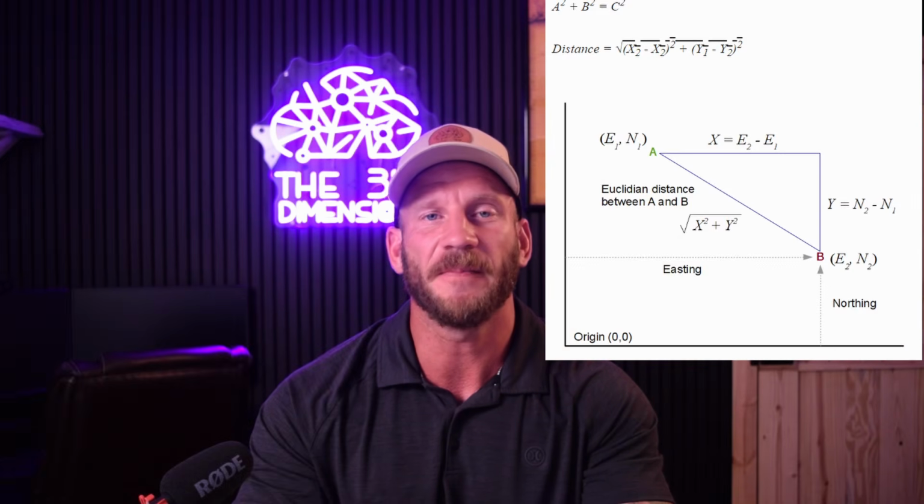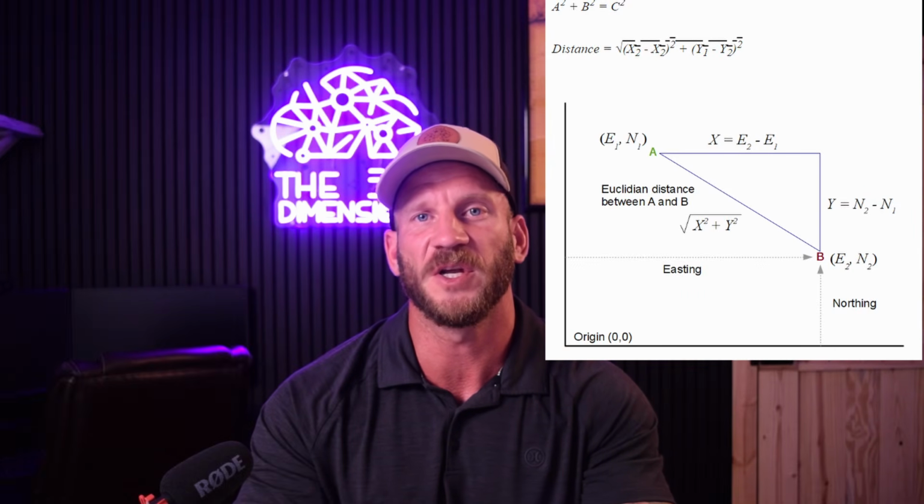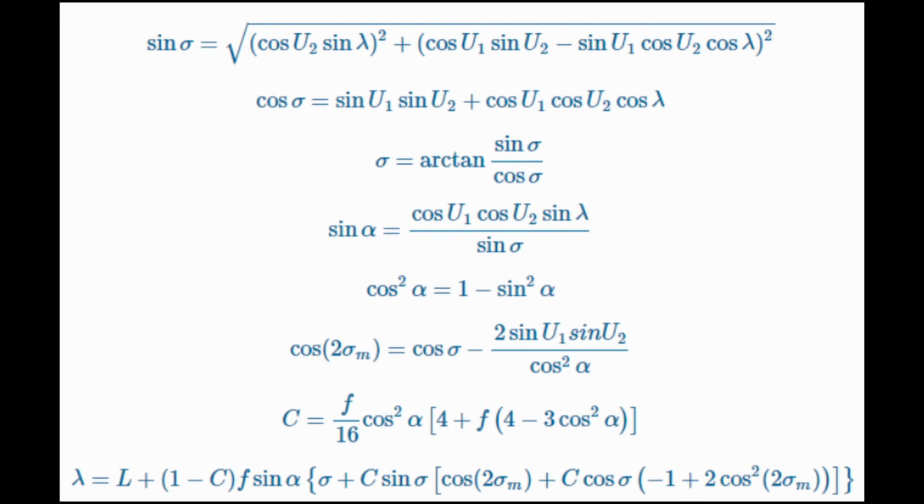This conversion from latitude and longitude to grid coordinates allows us to make 2D maps and also significantly simplifies the math we use to navigate in our maps, such as calculating distances, areas, and angles. If you've never done spherical trigonometry, take my word for it. Something as simple as inversing between 2 points that have northings and eastings becomes quite the task when those points are in latitude and longitude. So what's the issue here?